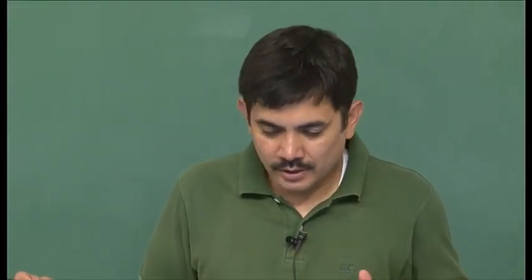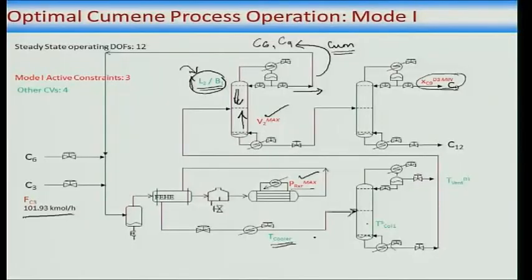Okay. Now what else? Okay, now let us go further. So, we have got feed fixed 1, 3 active constraints, that is 1 plus 3, 4, plus these 4 things I have just explained, that makes it 8, and what that leaves are 4 unconstrained degrees of freedom, which are economically quite important, and I will tell you why they are economically important, and these are put here.